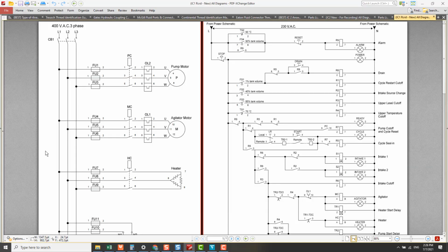When you measure the voltage here, let's say the circuit is good, the current will flow through here to point 1 and branch out into 2 paths. One path goes to the alarm lighting load, and the other goes to the multimeter, and we register voltage. If upstream has an open circuit or loose connection, no current will flow to point 1. Hence, the voltage measured will be 0 volt, as what happened just now.